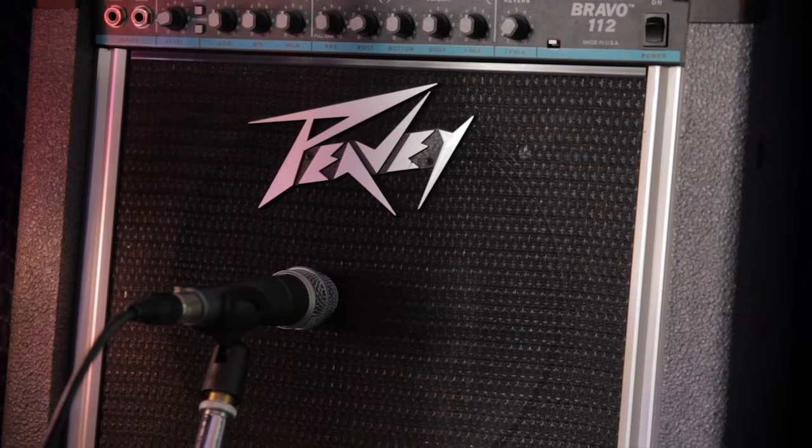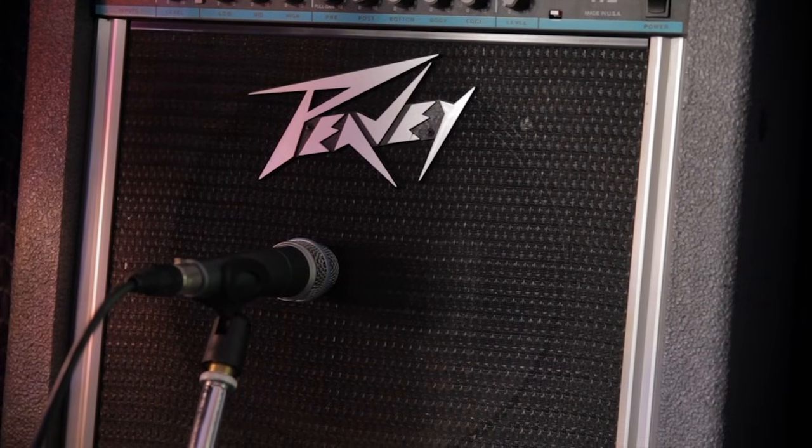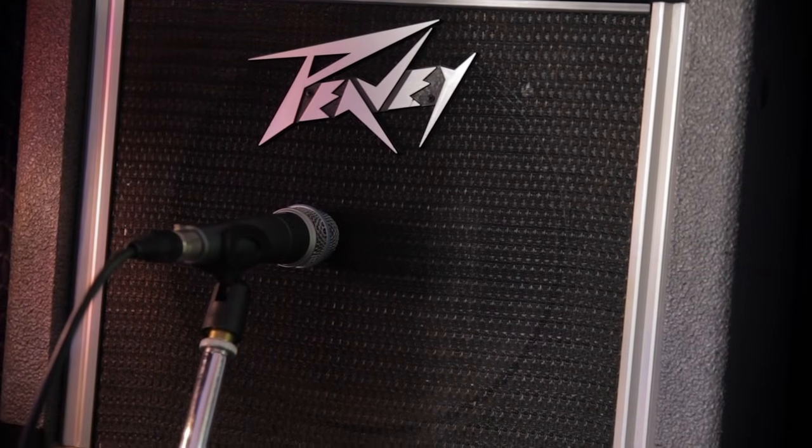The microphone is positioned right in the center of the cone, and it's maybe 2 to 3 inches from the cone. Now, setting up the microphone this way, pointing directly towards the center of the cone, will give you a good amount of high frequency response. As you move the microphone away from the center of the cone, you'll get less high frequency detail.